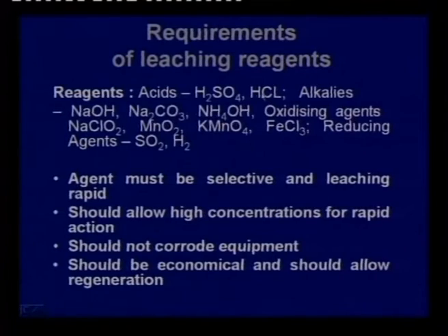Now, essentially in hydrometallurgy we need a concentrate which will be leached. During leaching, generally we take the metallic values in solution and the gangue is rejected in the solids, but the opposite of that is also done. We saw in the case of monazite leaching by alkali in our country, alkalis dissolve away the undesirables, and the desirable part remains in the insoluble residue.